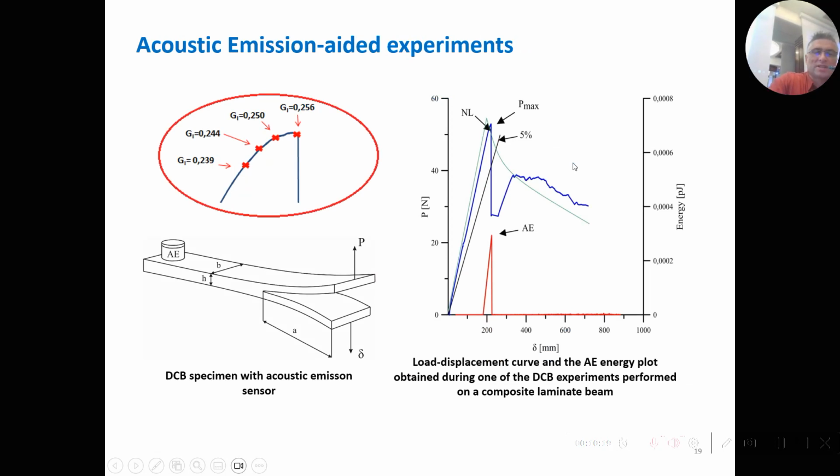Next, which is actually in the title of the presentation, I would like to tell you about some results of me and my PhD students about the acoustic emission applied to the experimental work. So, for example, for DCB opening specimen, we get such a curve like this in a navy color here. So there is a peak and there is some continuation of the saw-like line.